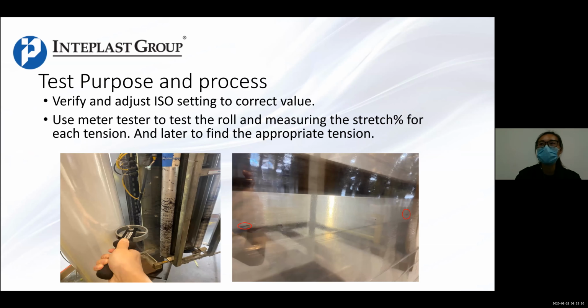First, I will make a database and see which film stretches lower than 250% or stretches too high, and then try to adjust tension and speed to let stretch get to 250%. When I test,